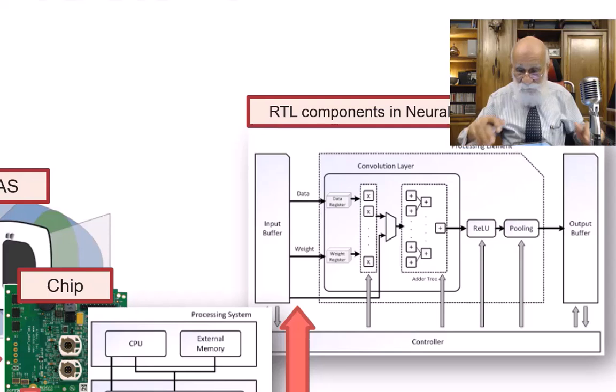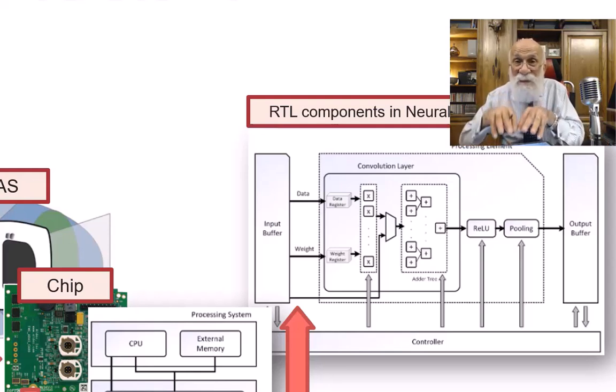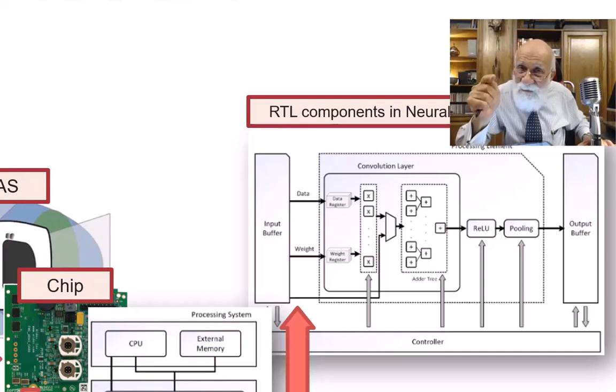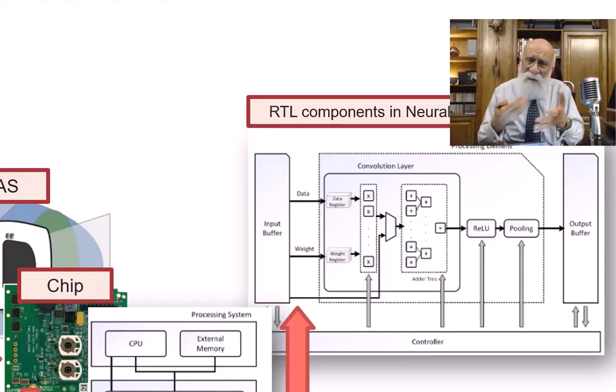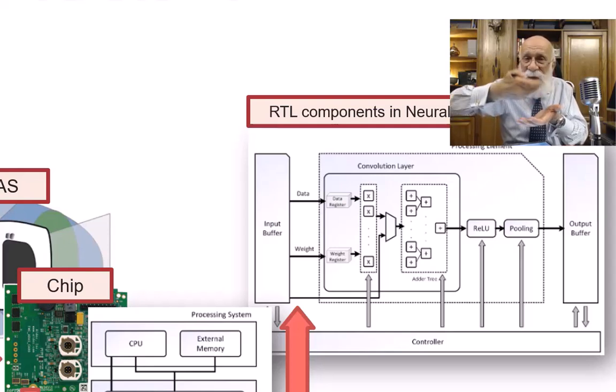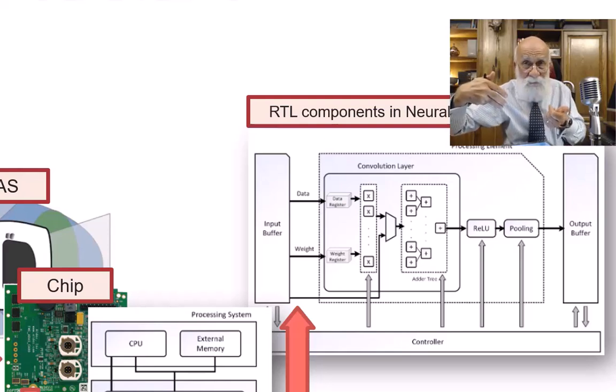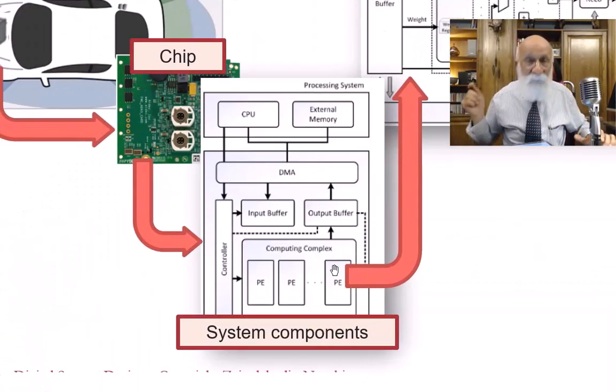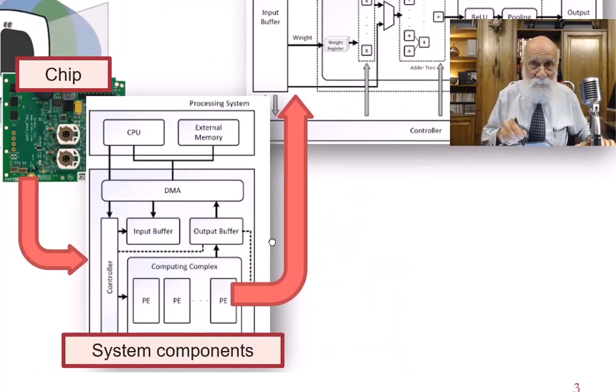Once we understand this, once we see these little components in terms of those little transistors, then we say, well, the same way we put these little transistors together to build an adder, to build a subtractor, to build a logic selector, the same way we can take these multipliers and adders and put these together to build a processing element.